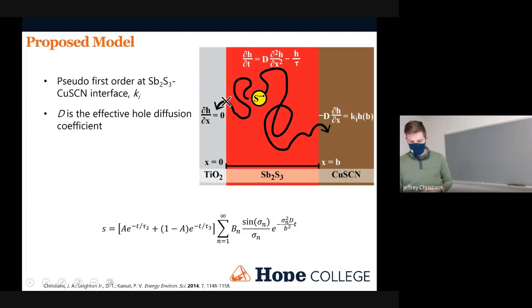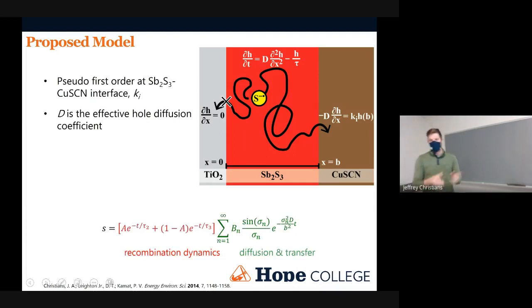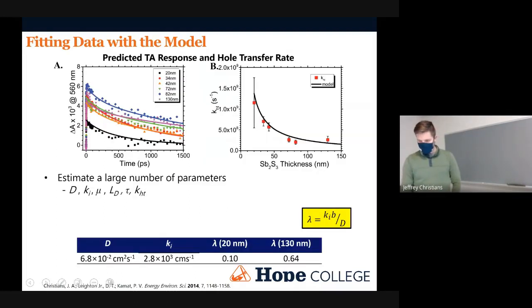Similar kinds of solutions. It got a little bit messier because the part in red is the natural recombination, the electrons coming down and giving off heat. But hopefully you see some of the same kinds of solutions in there. Then we could fit some of the data that we took, some of these snapshots, to this model and pull out a diffusion constant and K, which is basically the convection coefficient, but for charges.